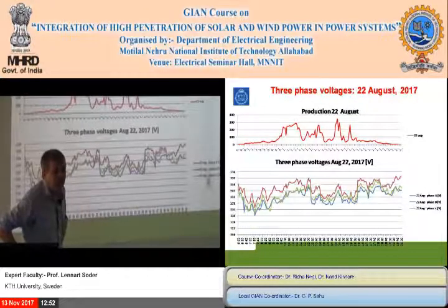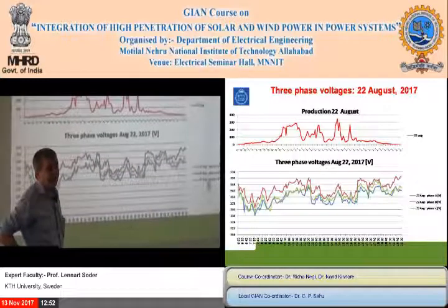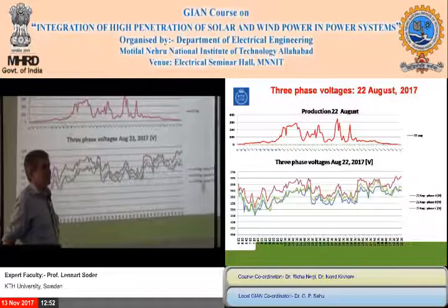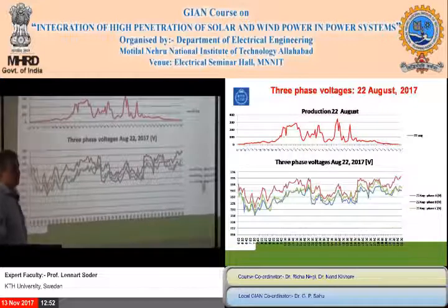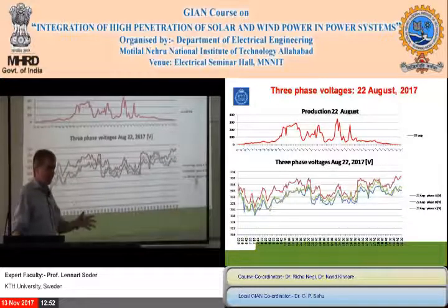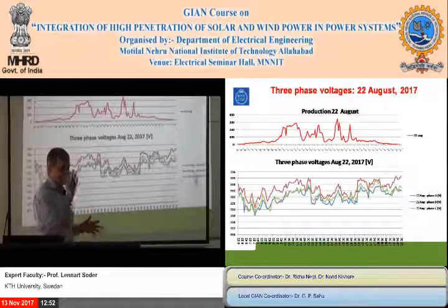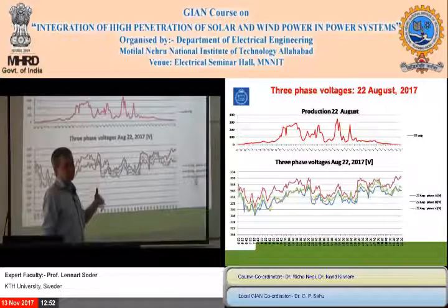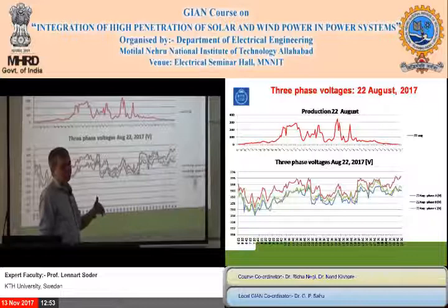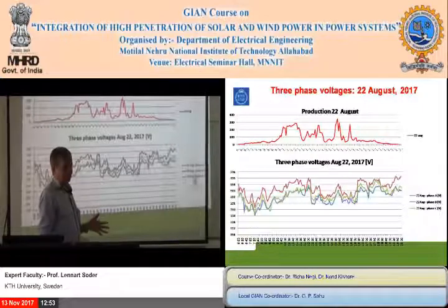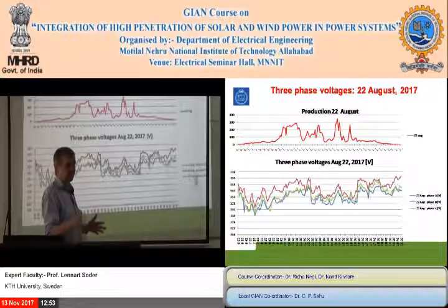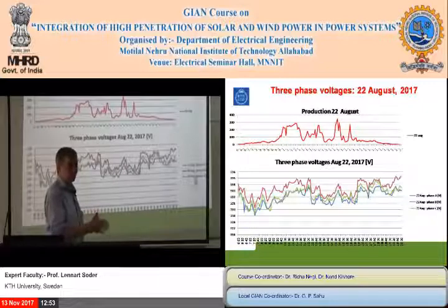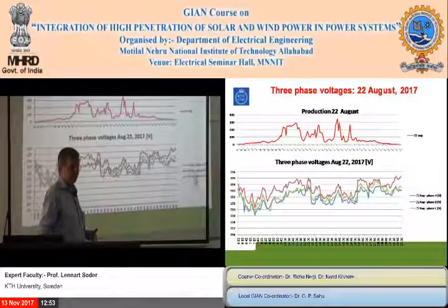It is disconnected suddenly, and how is the voltage maintained, during the export condition? That's okay. That's one of the security issues. If I have a house that is exporting and the grid fails, then of course it can be dangerous. But then you have security systems. It's of course important that you can identify that the grid is not working, so that I have to stop production.